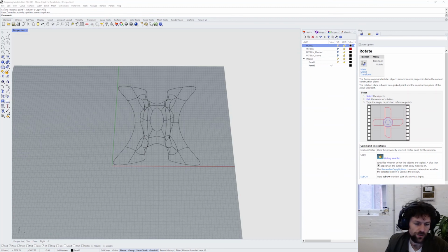Okay, that pretty much goes through everything that we need to know for preparing models for mixed reality. Joining objects, meshing objects where necessary, keeping objects at the origin, using line work and curves where possible, adjusting materiality to ensure that objects are always visible, and tweaking model locations and files so that they're aligned with the origin.